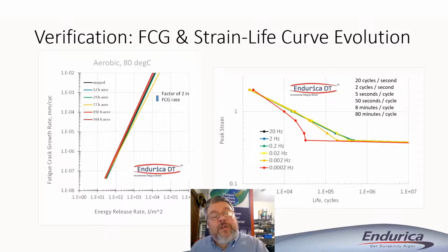So at first the strength gets a little bit bigger. In this case, that's what we observed in the experiment. But eventually, of course, as you impart enough aging, then the crack growth rate curve begins to shift to the left, and we start to see a weaker material where cracks grow faster, and so you can see that evolution in the time-dependent crack growth rate curve.